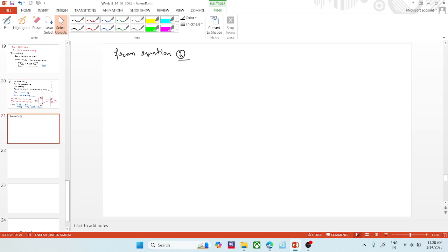Q dot CW we are having 141157. It is in kilowatt, so I will multiply it by 10 to the power 3 to convert it into watt. Then the U value we are having is 2560. Then this overall heat transfer area A naught we have to determine, and the LMTD value we are having is 4.228.